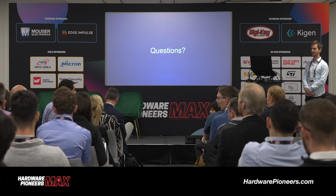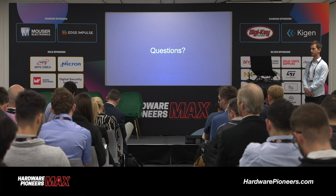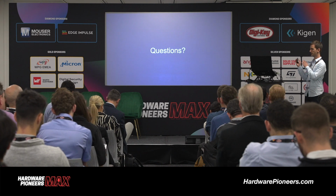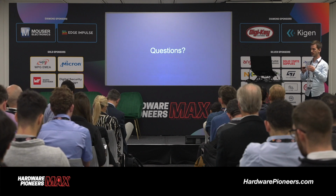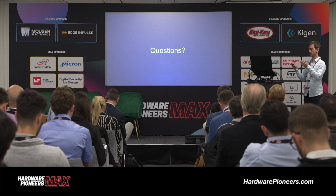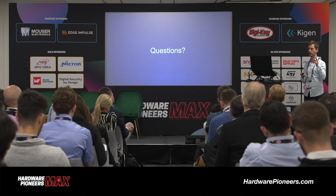Hello. Regarding the embedded devices, a lot of focus is also around power consumption. Do you think this technology could also be used on battery-powered sensors or devices? Of course. You could either use machine learning itself directly on the outputs of the battery to improve the lifetime of the battery, or you could do it by tweaking the way you use the machine learning features in your final code. Especially if you use a very low power microcontroller, usually you want to stay in sleep mode for as long as possible and then only wake up to do something useful.